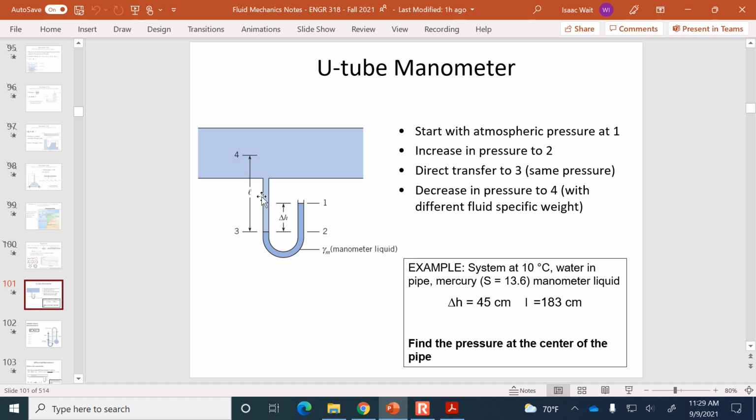So I just wanted to make you aware that we're on a little bit thinner ice when we go from the opening of that tube, which is, inside the tube, the water's not moving, but then as soon as you go outside of the static U-tube and into this environment where the water's swirling past, the pressure change might be slightly different than what's described by the hydrostatic equation. All right. Any questions on this example?